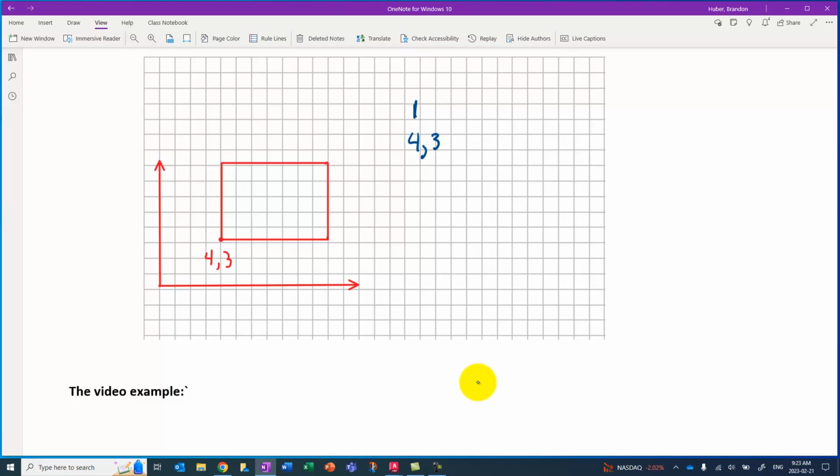And then from there we're going to do polar coordinates. So moving to the right here in a relative move, we're moving 7 boxes to here, and we're moving at 0 degrees. So we could type this in as @7<0. Moving vertically now to this point, we're moving by 5 boxes. So it starts out just like the relative coordinate, but then we put in the angle, and a vertical move straight up would be 90.